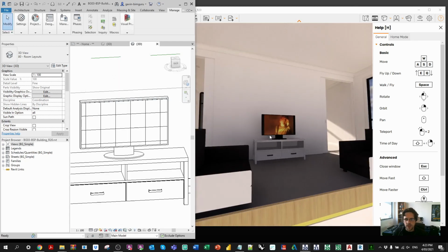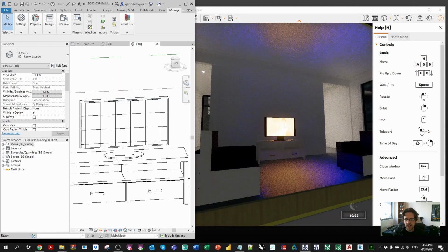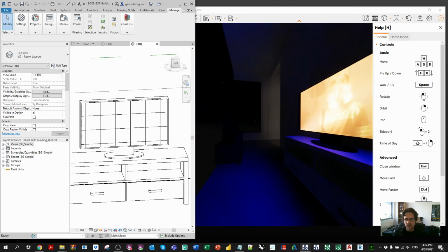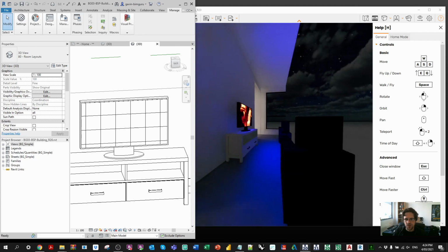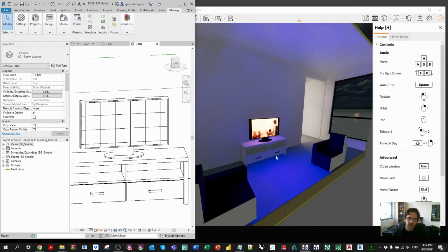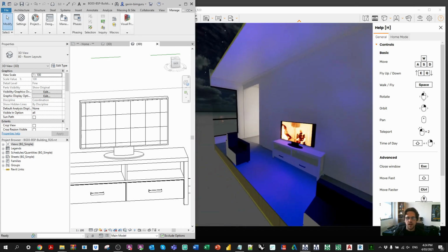You will notice that if I go to nighttime, it will project light onto the scene, but notice how it's this strange sort of blue color. Now I haven't found a real way to control that color. For some reason it always seems to come out blue. I'm not sure if it's trying to average the color of something inside the video itself, but it always seems to come out this blue color, so it's not quite what you'd want. So you may wish to build a lighting family to put in front of this instead to get the exact color that you want it to be.